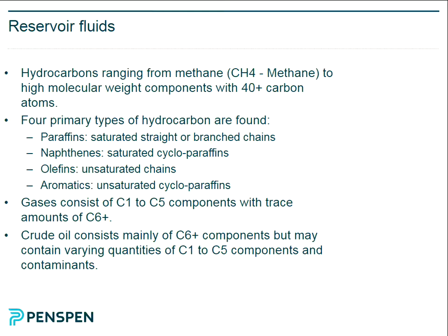There are acid gases, which can cause corrosion in your pipeline. I'm sure you've covered this in other lectures, but CO2 is one, and H2S is another. CO2 causes corrosion. H2S, in some situations, can actually help with corrosion, but obviously has other issues. Hydrogen cracking, for example, hydrogen-induced cracking, HIC. It's very nasty for materials.